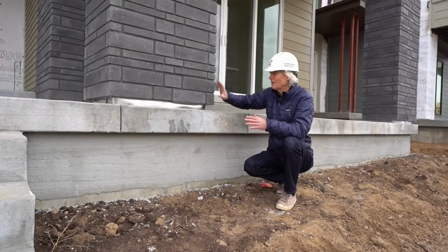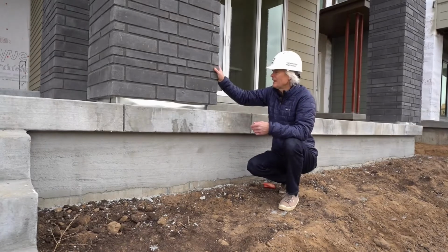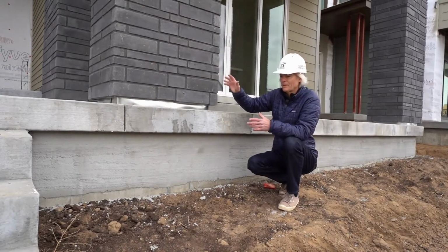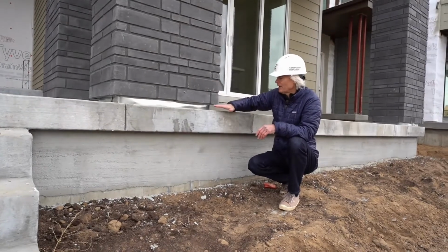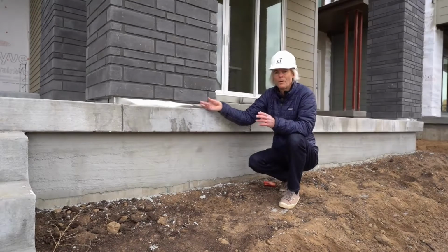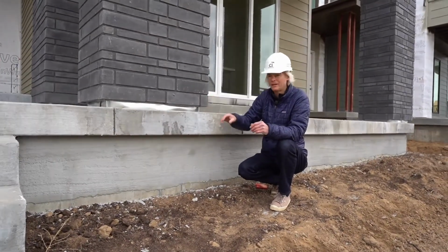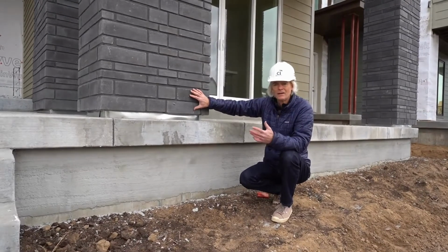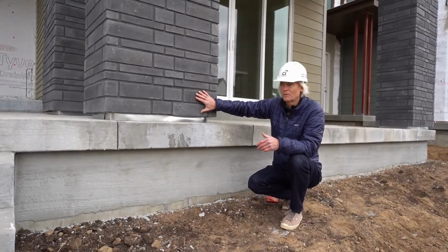So here we have a sort of thick column to the porch on this house. It's framed with wood framed materials, sheathing, and then this thin brick is applied to it, to the patio, and I can see that it's a thin brick material. What I want to do is we see one right behind us in the next house that doesn't have the thin brick applied yet. This is going to be a lot like a masonry stone veneer that we'd see on a building, a scratch coat. This thin brick gets installed.